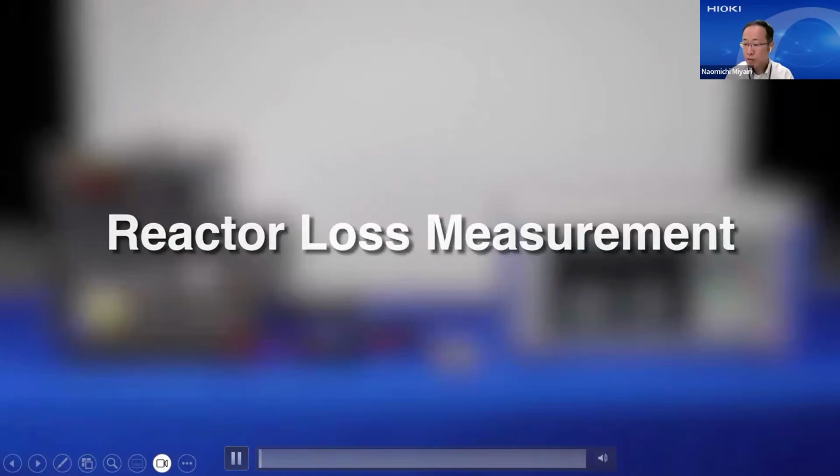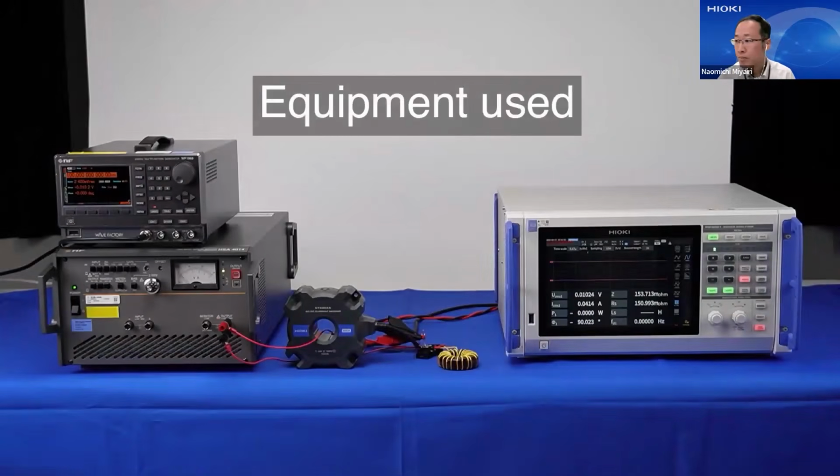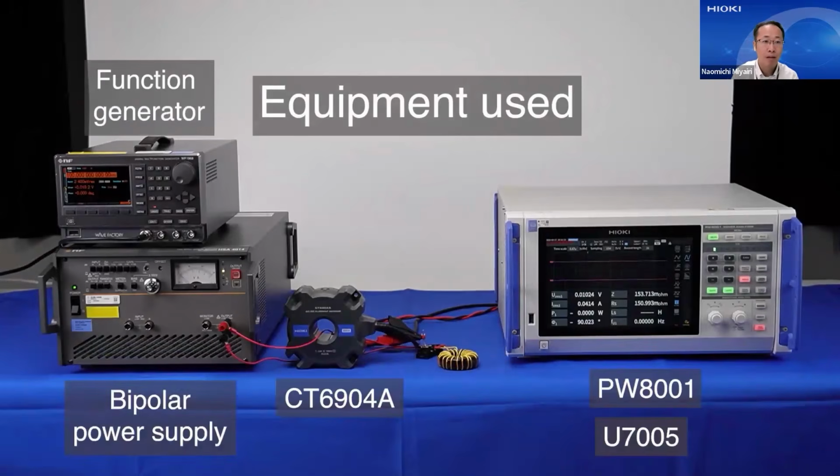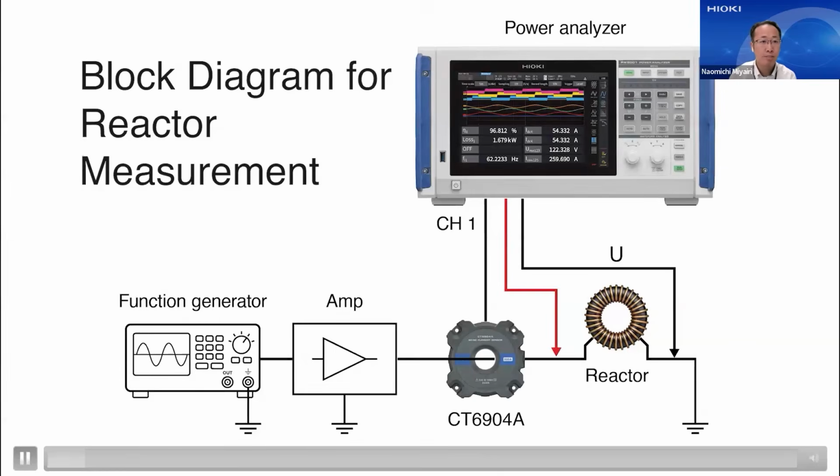Okay, I will now introduce inductor loss measurement. The equipment used is the power analyzer PW8001, input module US7005, and the current sensor CT6904A, bipolar power supply, and function generator as a signal generator. So this is a block diagram for inductor loss measurement.